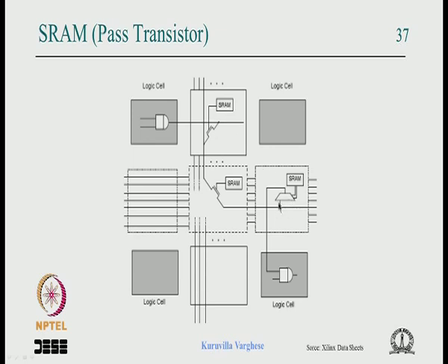So there is a flip flop here, and you see there is a 2-to-1 mux. You see here there are a lot of horizontal lines, and now you can have a kind of crossbar connection. We said that an n by n crossbar uses an n to 1 multiplexer. So this is a kind of 1-to-1 multiplexer, but here you can think of, say, a 4-to-1 multiplexer, which allows you to connect any of the 4 horizontal wires to the input of a logic cell. So if there are 4 inputs, then you have 2 select lines, so there are 2 flip flops connected to the select lines. So you have the ability to program 00, 01, 10, 11 and so on.